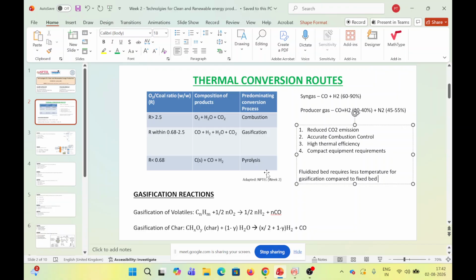In the second case, that is your quench, the hot raw syngas enters into a quench ring where it is shock cooled by the water. That steam then moves to the steam boiler where it rotates the steam turbine to produce electrical power. So this is about recovering heat.